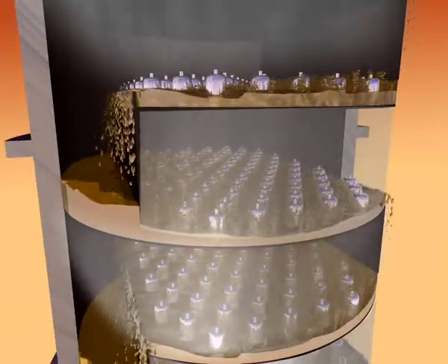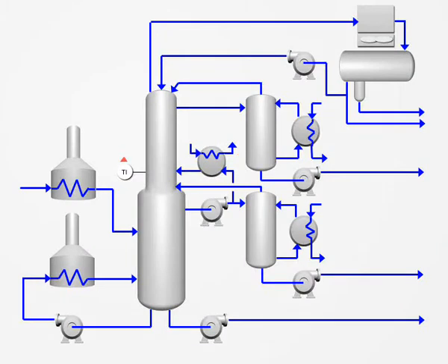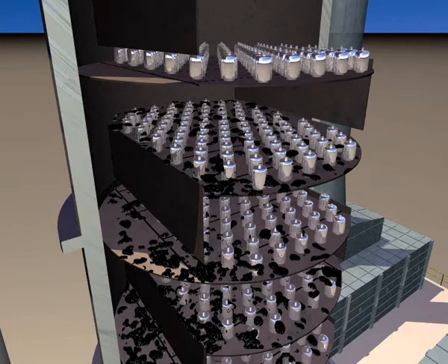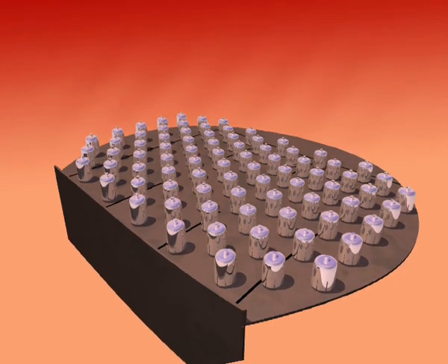In the situation where the liquid level is very low, the temperature will rise because the liquid vapor rate is out of balance. Overheating of the oil can result in coking, leaving behind a solid residue that could plug the trays. If the liquid level is completely lost and the tray is running dry, the temperature of the internals itself will increase. The liquid acts as a heat sink to the heat the vapor is providing, and when lost, the trays can warp and bend out of shape because of the excessive heat.